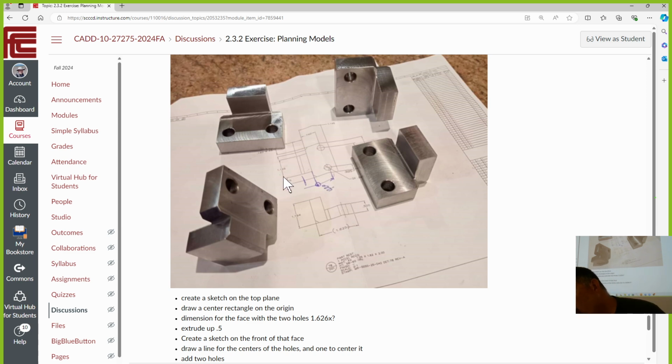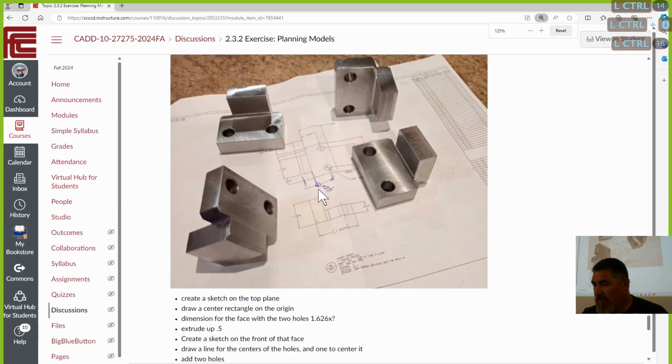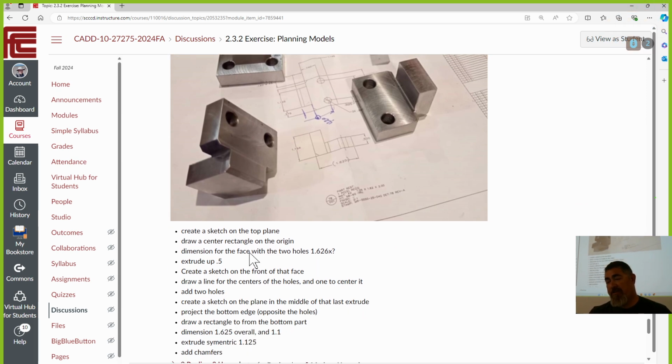Actually, so I'm gonna have to do math anyway. No, I'll just do that. Borrow some figures. So actually, by doing that, I'd have to change my whole plan if I want to use this dimension. I would draw this, extrude it, and then just draw on this face, and then now I can actually put in that 0.375 dimension right there to help control the width of it.